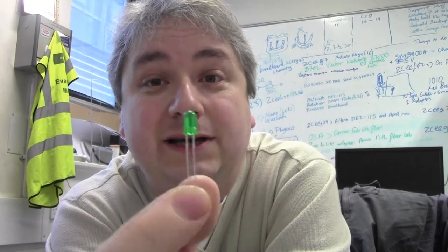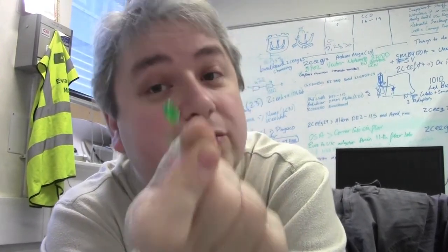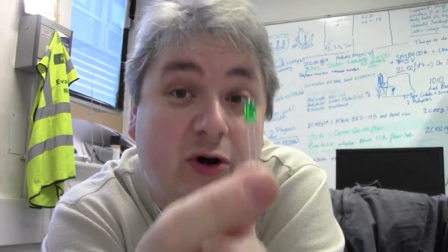Now, standard silicon diode, 0.7 volts. You need to bias it with 0.7 volts before it efficiently conducts current, because you can get it conducting a bit lower, but let's not be too anal about it. 0.7 volts, it operates perfectly fine. LEDs, on the other hand, because they emit light, and the way they emit light is we chuck a load of impurities at them to turn them into a very crappy diode. Their forward bias characteristics are a lot higher.